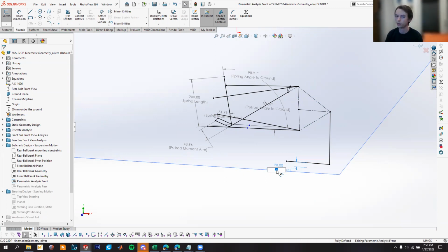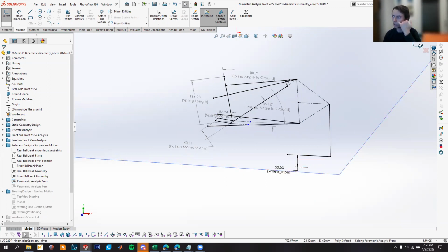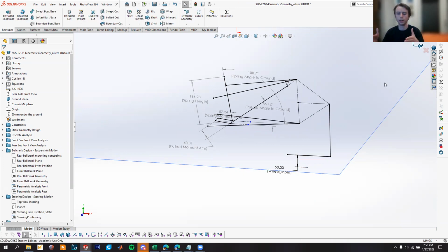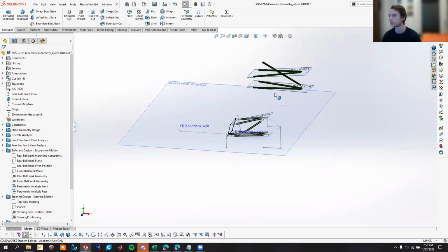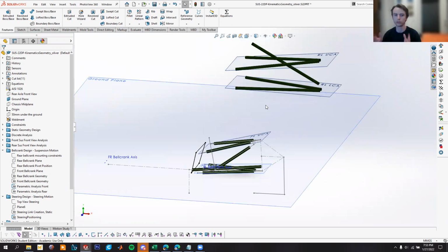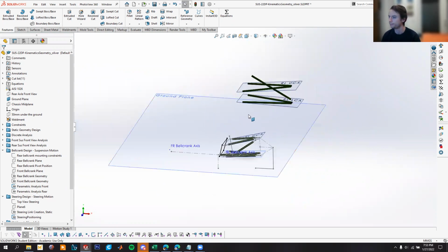That's the static angle away from perfectly center that the front tires, or rear tires for that matter, start at. For rear tires, we want slight toe in, so that as you accelerate, your tires are trying to push you into a straight line. For the front tires, we might start with a very slight toe out or very close to perfectly straightforward.